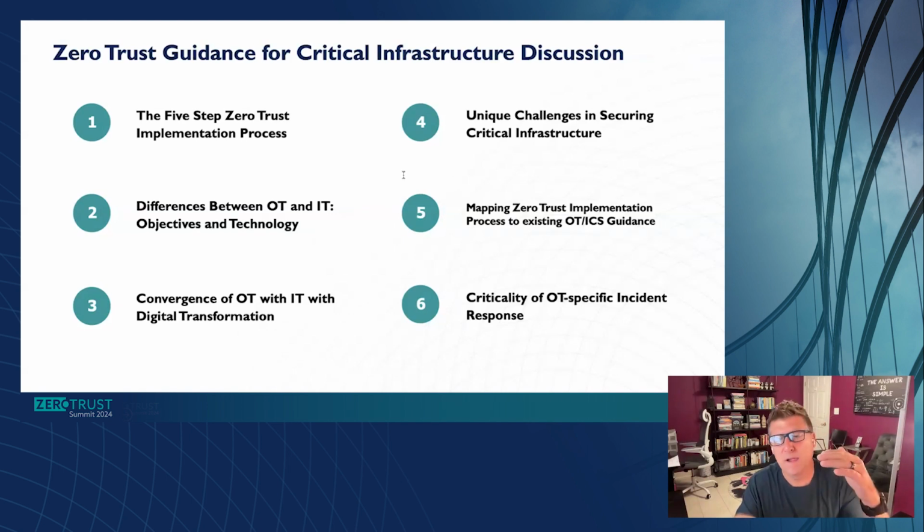Some really great ideas for leveraging the OSI network model, mapping to the Purdue levels and saying, great, it's probably a level 3 routing control that you want to apply to a flat network where it's industrial protocols and you don't have IP everywhere. So can you put something in front of it to create a choke point or a policy enforcement point?